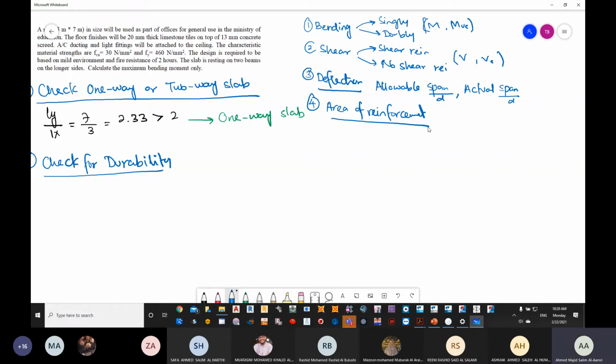We are designing for under reinforced section, and under reinforced section is not related to having something lesser than the required. In under reinforced section, you are having certain quantity of concrete and certain quantity of steel. In that, you are designing your element in such a way that the stress of steel will reach the maximum level before the maximum stress of concrete reaches its level.